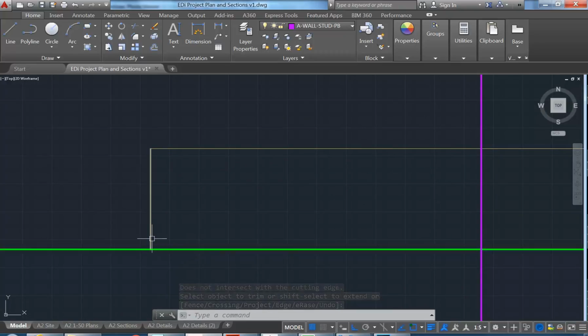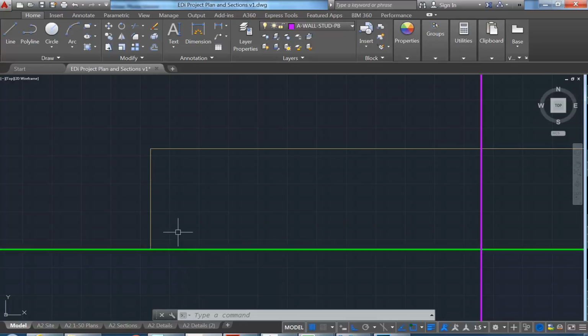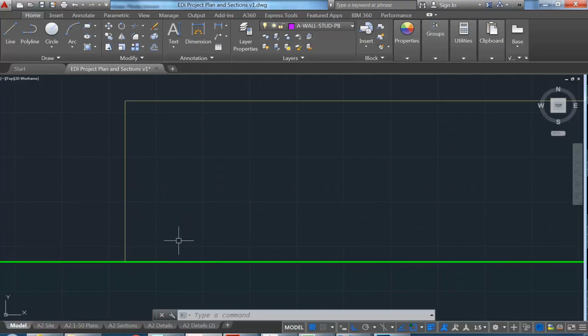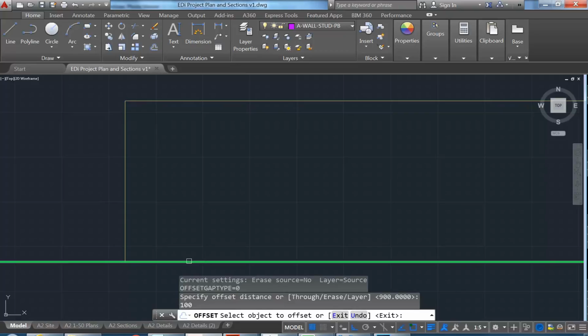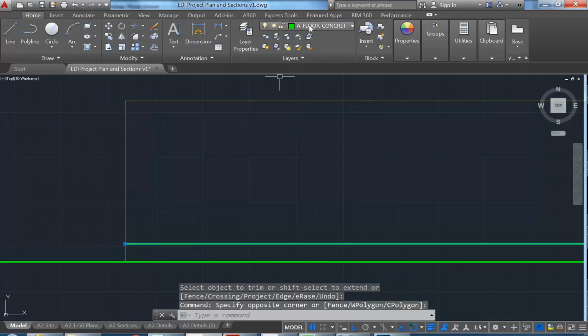What about then the cupboard doors? Where do they start? Can they start from the floor? Definitely 10 centimetres or so for kickboard, and it's not just for kicking, it's so your toes don't get cut off by the door, which will happen. I've seen people do cupboard doors down to the floor and think they're being really clever and reinventing kitchen design, and it's not pleasant when you see what it can do. So always have a kickboard or some raised amount from the floor. 100mm is standard, so that's good. And so again, onto my joinery layer.